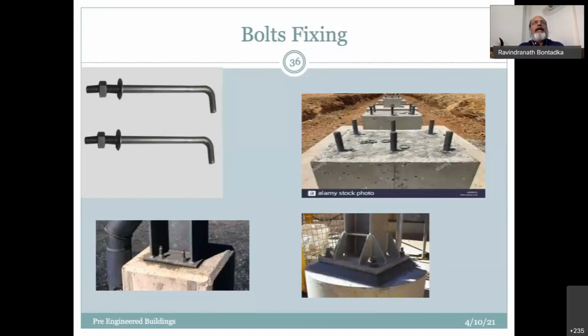There should not be any tolerances with that, because they are coming with particular bolts, and then the sizes and the distances. So column to column distances or bolt to bolt distance have to be properly ensured at site, because once it is cast, you cannot undo that, because there will be a different process and it will be a very costly one to adopt. So this is how it comes.